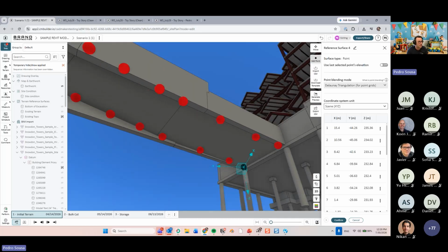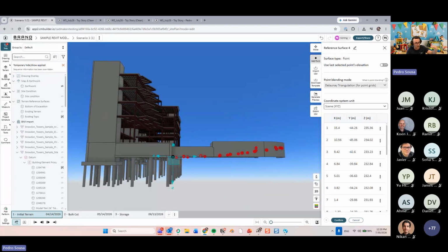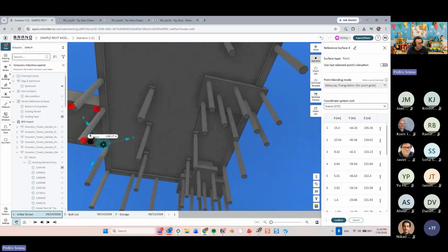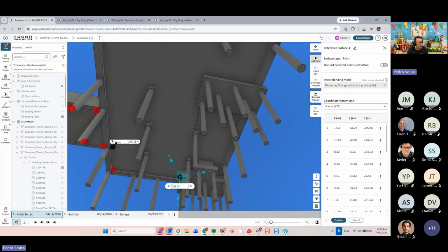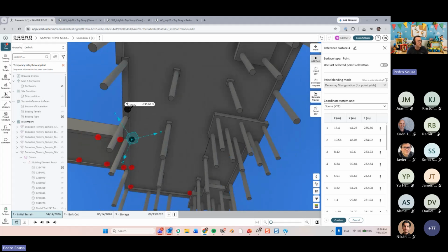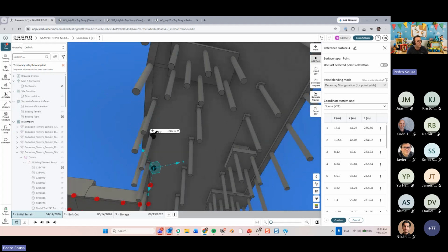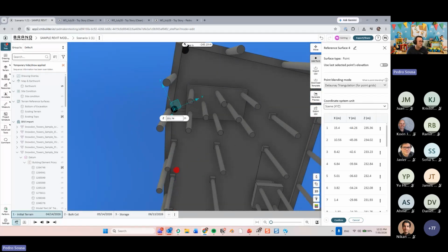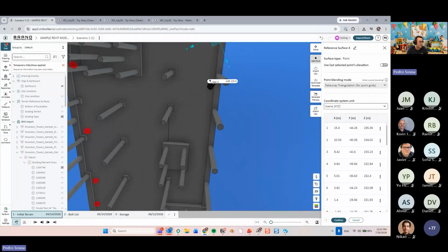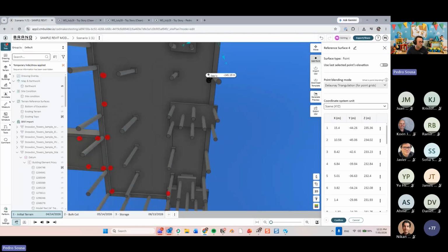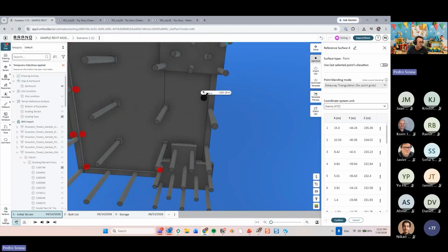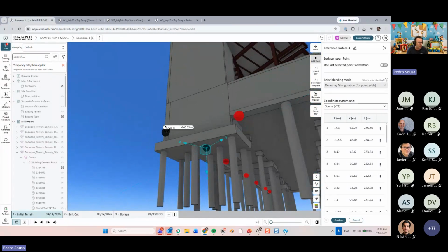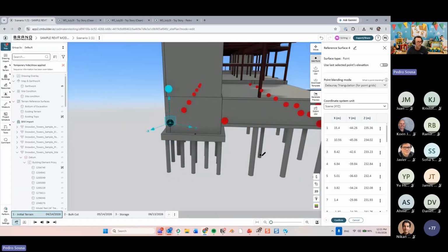Okay, so I traced my ramp over there. You can see that the points are following the shape of the ramp. And then for my slabs over here, I can just trace whatever I want, and I will follow that here, here, here. Since these points are all at the same elevation, I don't need to place a lot of them, because the extrapolation for the surface creation in between the points will be flat. So you don't need to worry too much about that. There's another part over here that I'm going to ignore, and then I'll create another point over here at this elevation.